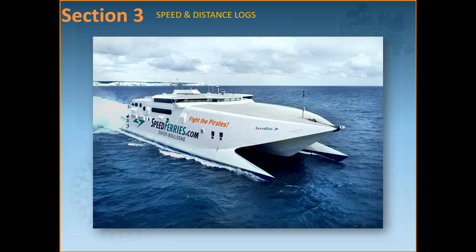It is claimed to be more accurate than the other types of logs and is particularly useful because in shallow water it can measure speed over the ground, in deep water it can measure speed through the water, and in medium to shallow depths it can measure either speed over the ground or speed through the water. If you fit a transverse axis beam to the Doppler log, it can also measure speed sideways, which is very useful when berthing, especially large ships.